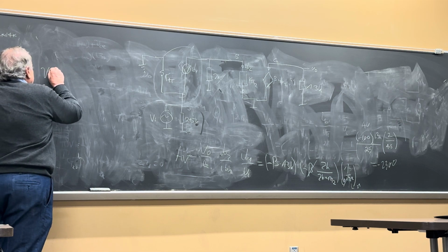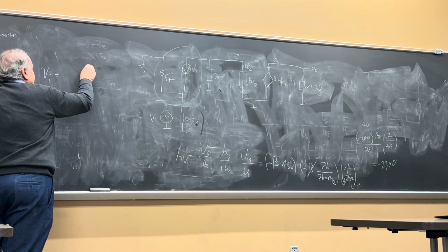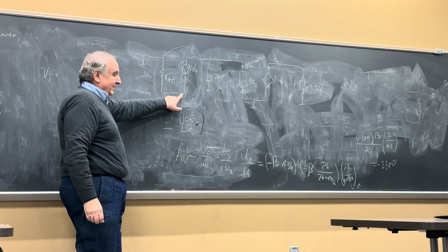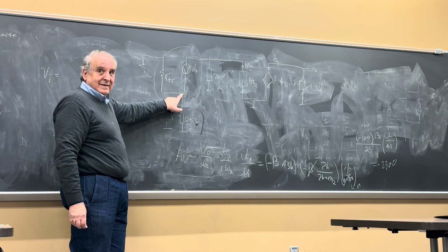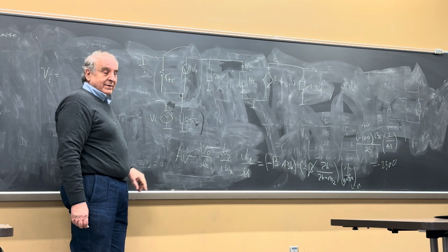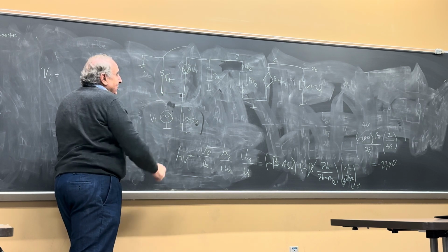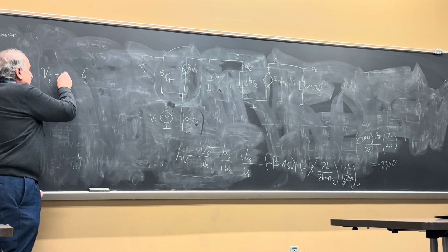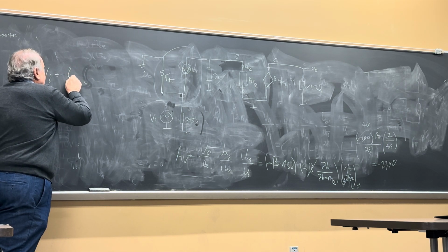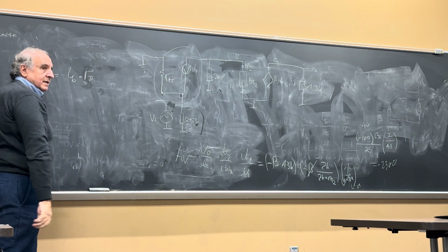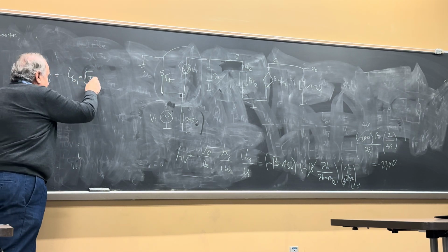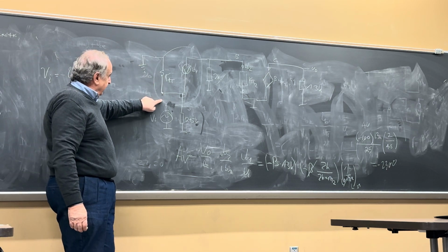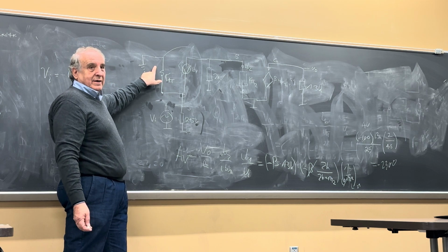Take a look here. Vn is equal to something IB. What is that? This is Vn, right? Vn connected here. This is 0. What's this voltage in terms of IB? 0 minus Vn, minus IB R pi, right? Is that right? IB1, R pi 1? You see that or not? Okay, because 0 minus Vn divided by R pi 1 is equal IB.